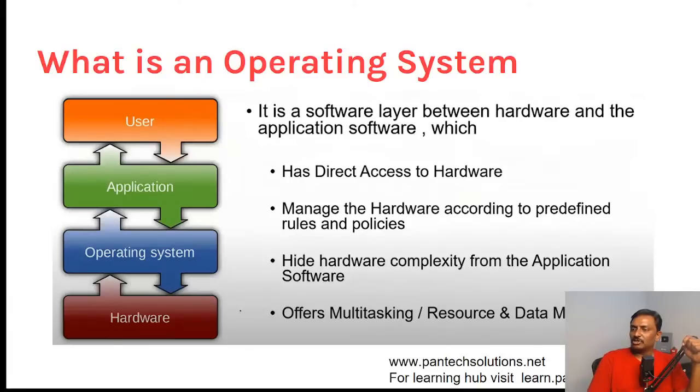Is Bluetooth based on UART? No, Bluetooth modules can use a UART interface to interface with the microcontroller. For example, take the HC05. The way you interface the Bluetooth module with the microcontroller is through UART.